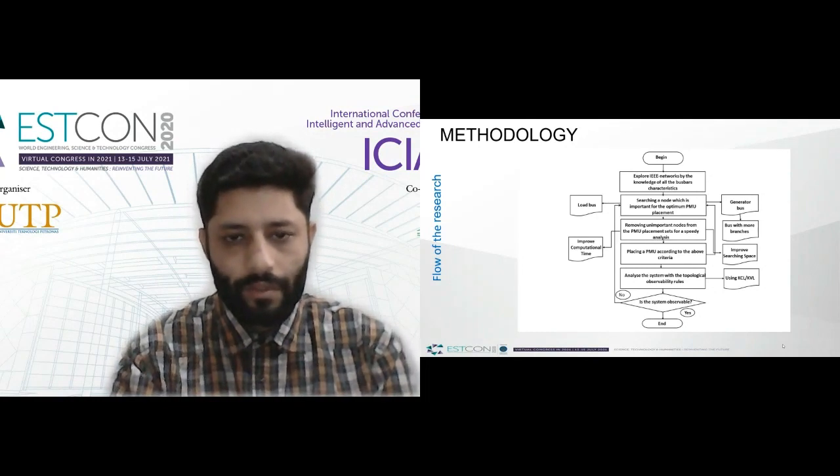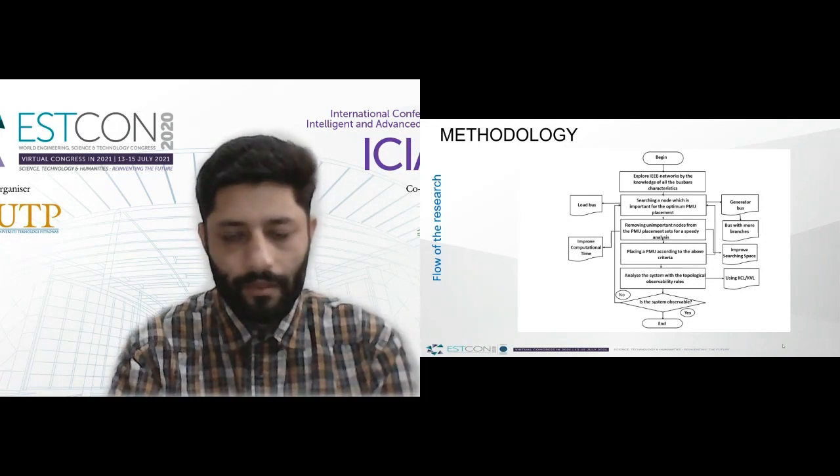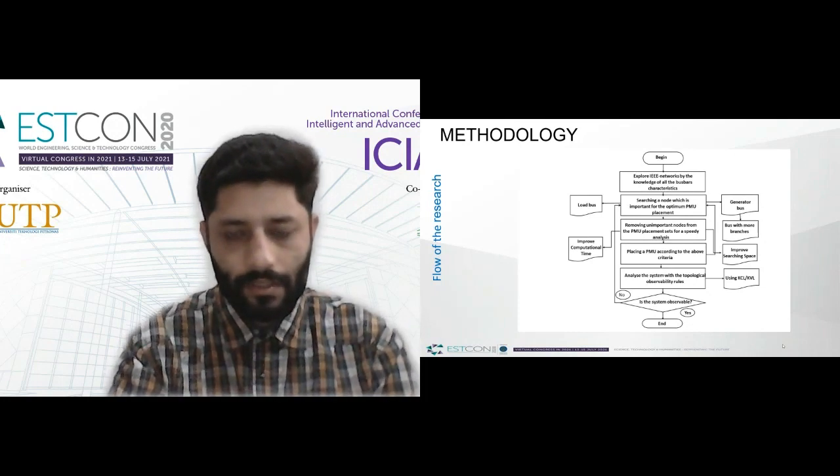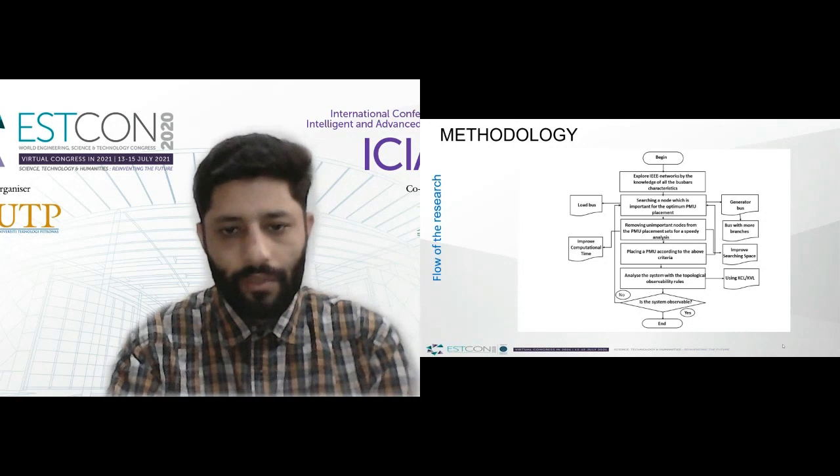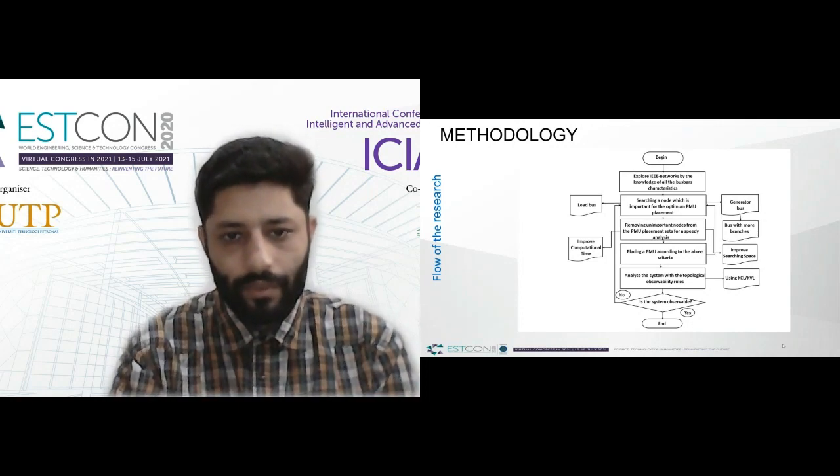The nodes are load buses and generator buses, and among those buses we have focused on the buses which have more number of branches. So the preference will be given to those buses which have more number of branches, specifically load buses and generator buses, and then we move on to removing the unimportant nodes, those that do not have these kinds of characteristics. Excluding these nodes improves the computational efficiency and reduces the searching space of the network.